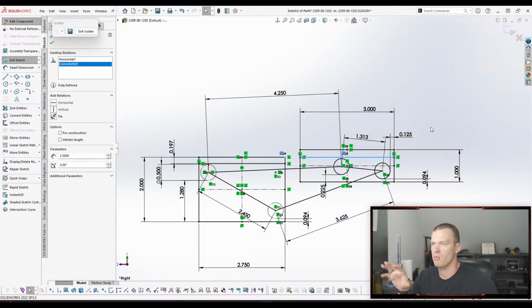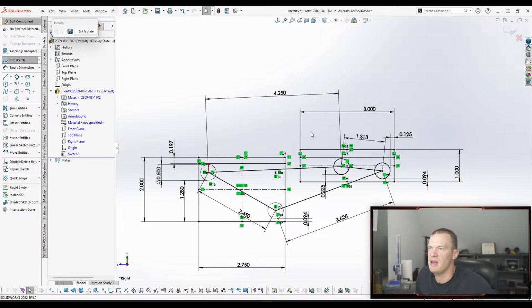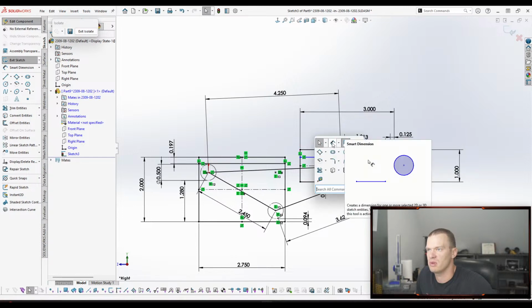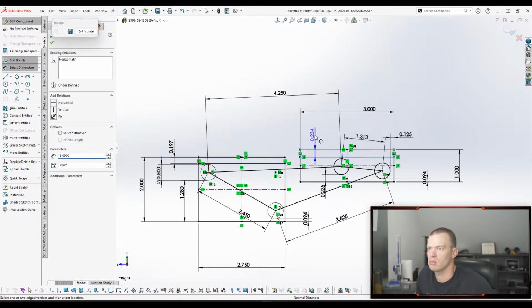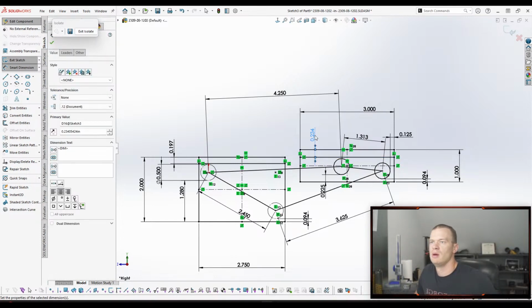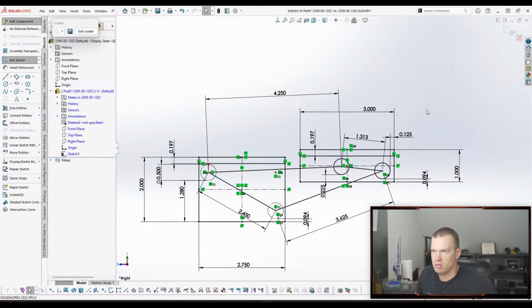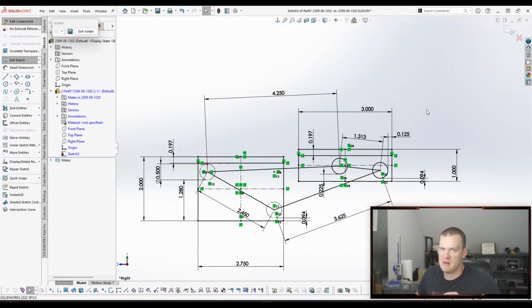But as you're drawing more complex sketches, and obviously you're trying to keep them as simple as possible, as much as you can, but as you're drawing things, especially if you're trying to do motion or something like that, like what we're doing, really pay attention to when you create geometry, is it behaving the way that you want, right? A good way to test that is to draw something and then try and move it. Is it pivoting around? Is it just moving through space and staying square? That'll give you insights into maybe SolidWorks snapped to something that you didn't necessarily want.